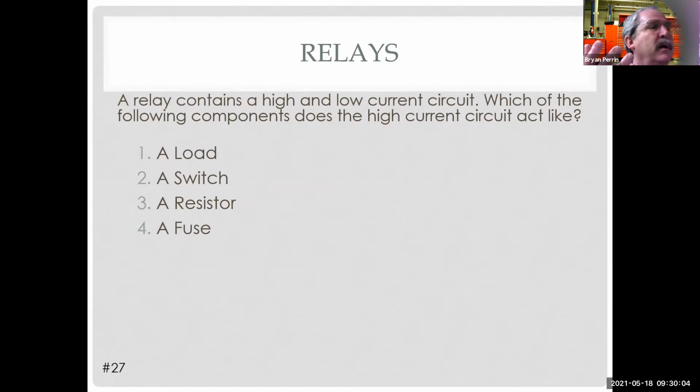What does it do? What is it supposed to have? And there's such a great test point because I divide a circuit. I divide the control side into two halves, and I can divide the load side into two halves. The switch, I can divide it.